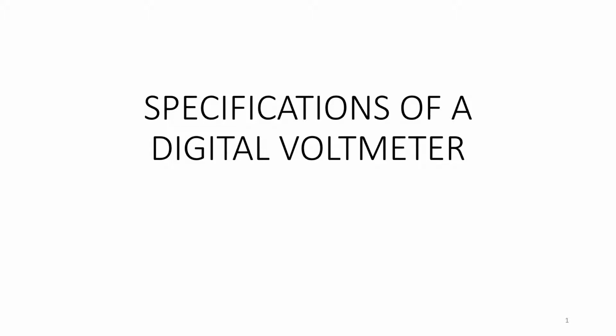Digital instruments are used to measure the voltage, current, the power, frequency, etc. To enable digital instruments to recognize information, inputs which are analog in nature must be converted to digital form. Hence, any digital instrument consists of an analog to digital converter in its input stage.